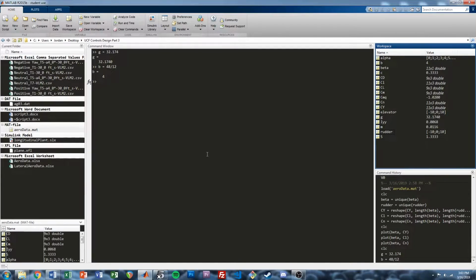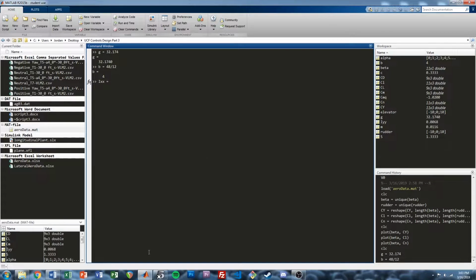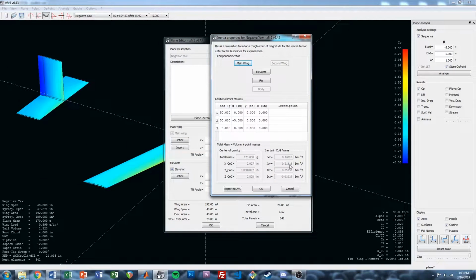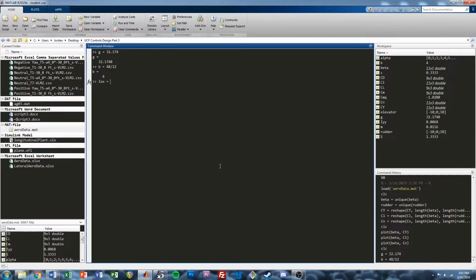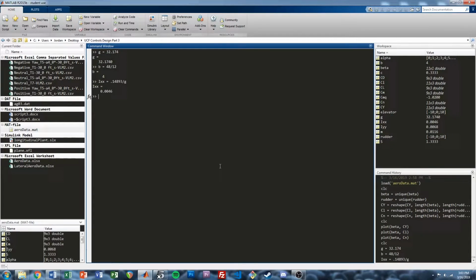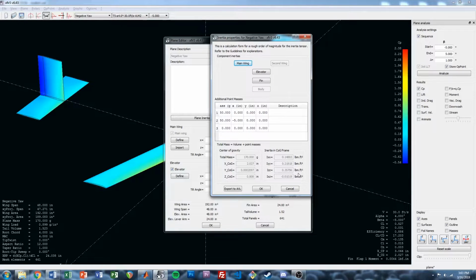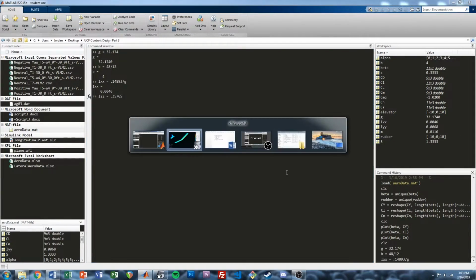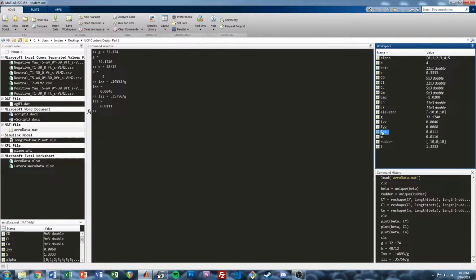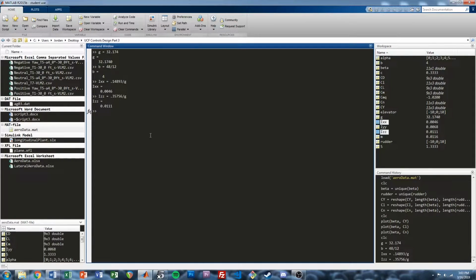We're also going to need updated moments of inertia. So we need IXX. We can go back to the plane editor, plane inertia. We can see IXX is 0.14893, and that is pound mass feet squared, so we need to get that to slug feet squared, so we'll divide by gravity. And then we also need IZZ for this design as well, which is 0.35765756. Divide by G again, and that G is just to go from pounds to slugs, so you're dividing by gravity. So I'm going to add in IZZ and IXX. That might be it for the mass properties.